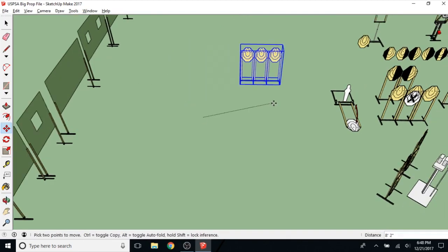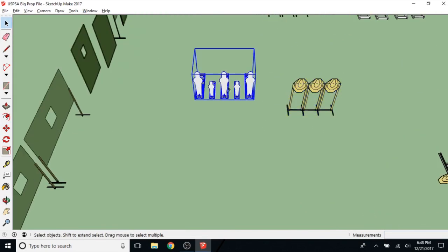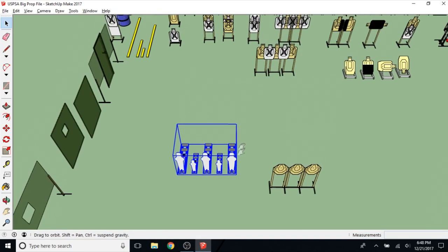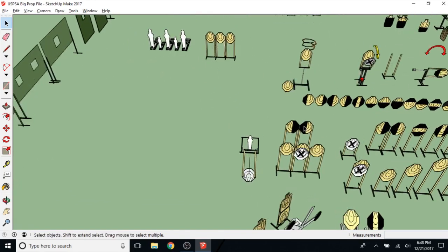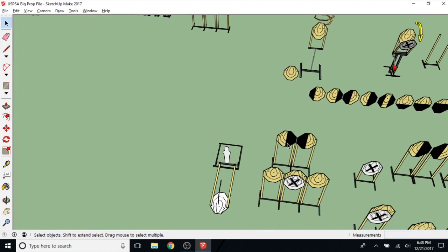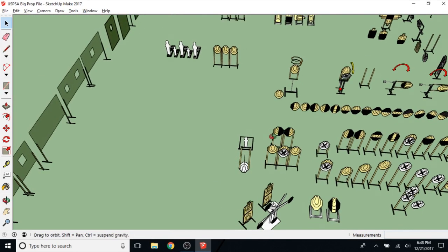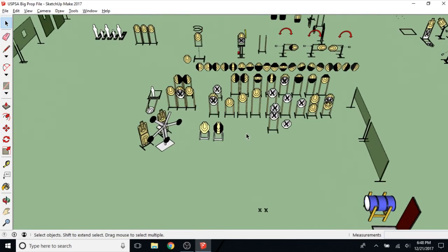If you had any desire to do that, you can see I did that with these pieces of steel here. And this array of targets, I believe I even did it with some of these as well. Just different target arrays that you like to use. You can save those together as a group, and then you can copy and paste it. You don't have to worry about trying to stick 2 targets close together in the correct reference in the stage you're trying to build. You can focus on just tossing stuff into the bay, moving it around, and going about your business.